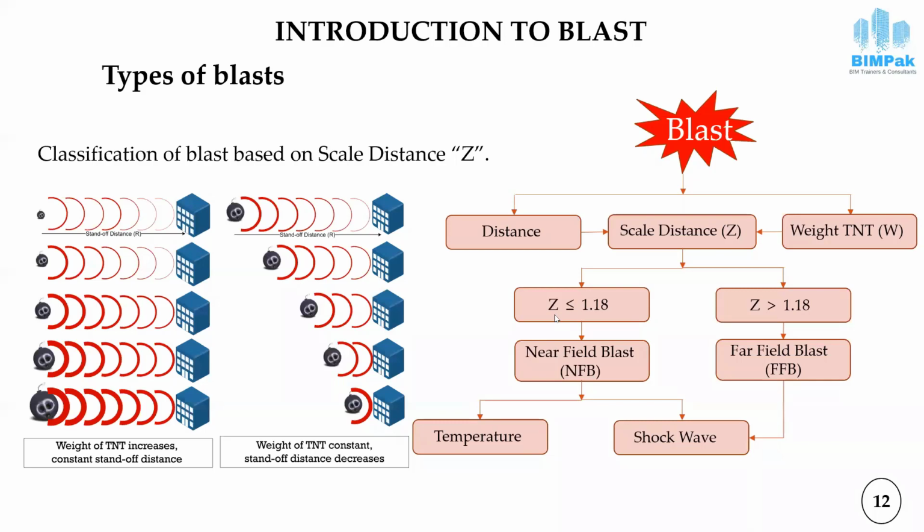It means that when the scale distance reduces to less than 1.18, the fireball will completely cover the target. So in that case, you have to consider the temperature effect in your planning and designing. In case of far field blast, you only have to consider the shock wave effect. In this type of blast, the temperature effect is not significant.